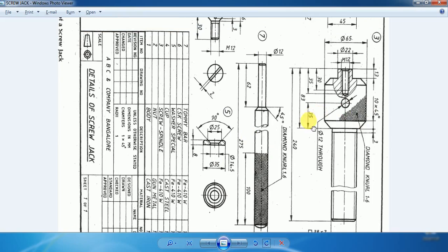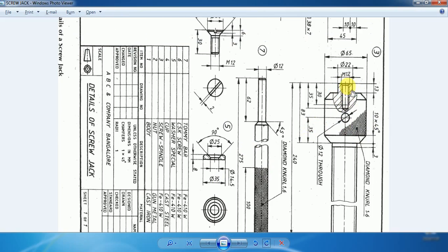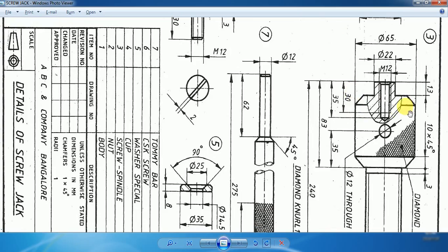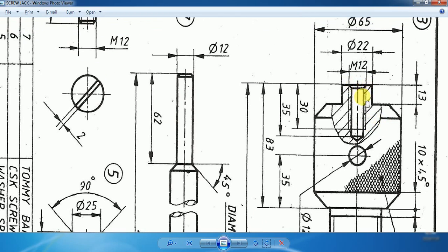Then our objective is to make this wall, which is actually the countersink wall. What is meant by countersink wall? As we move in the depth direction, the diameter is going to decrease. That is the countersink hole. On the top side the diameter is more, and as we move in the direction of the depth the diameter has slightly decreased, and then the diameter remains uniform for the remaining depth, and at the bottom of the hole there is a V bottom.